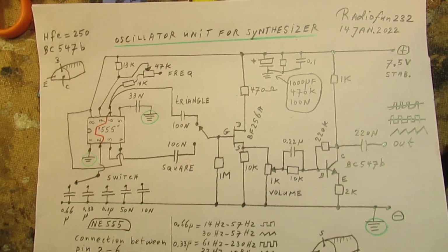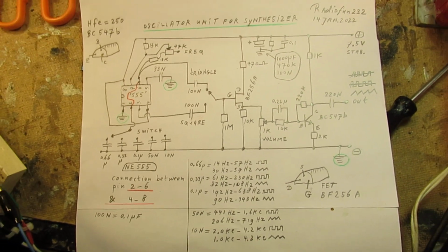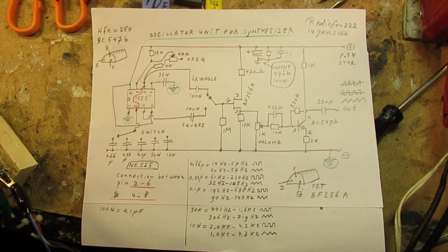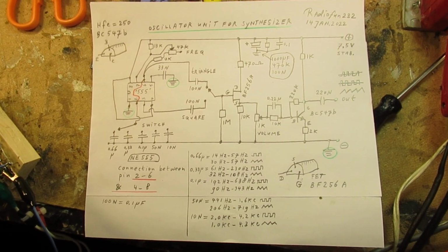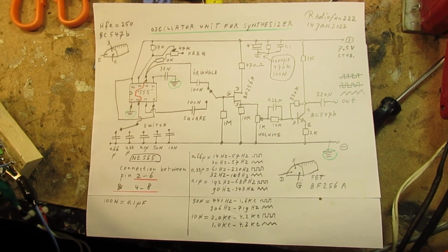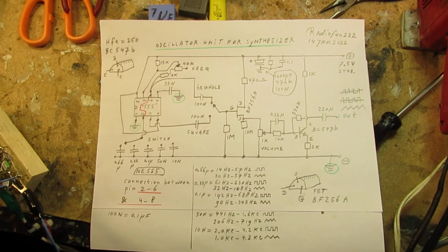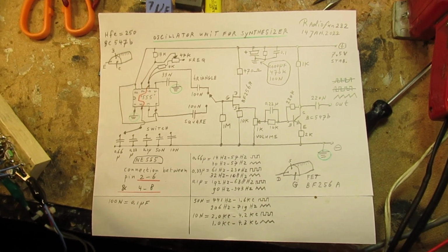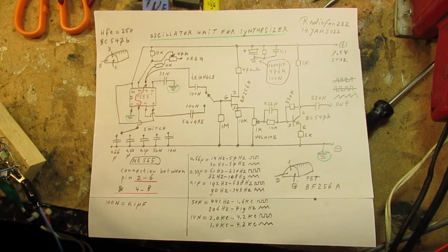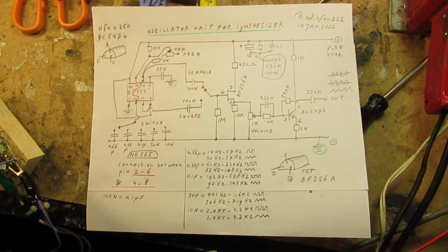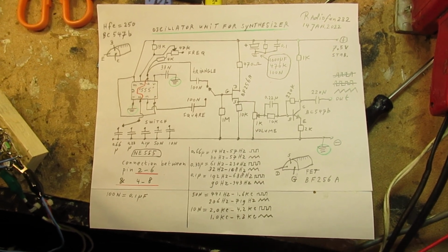of parasitic oscillations. You can, by the way, always expect parasitic oscillations in amplifiers, homebrew amplifiers, pre-amplifiers, etc. It has everything to do with the proper setup. So in many cases it's not a proper ground wiring, haywiring, etc.